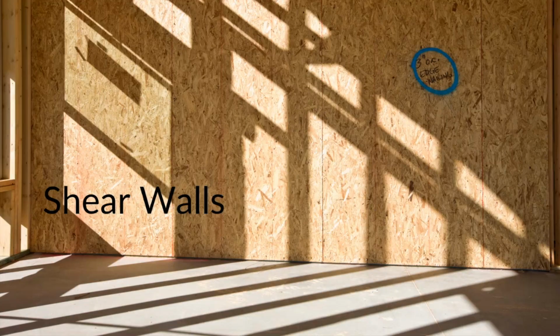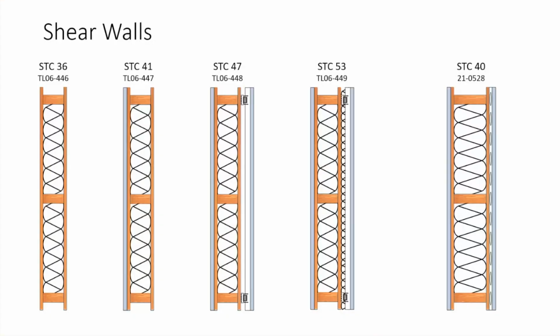All right, shear walls. Shear walls are kind of like where we've got isolation on one side of a wall and we want to mount something heavy. If you're only trying to mount something heavy on one side, you can put the isolation on the other side. Shear walls are similar. If you only need a shear panel on one side of the wall, you can try and put your isolation on the non-shear side, and then that can work just fine.